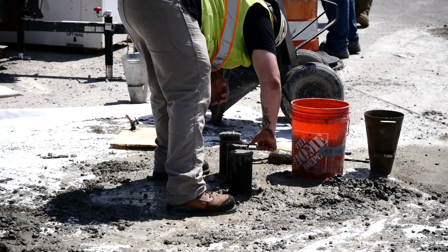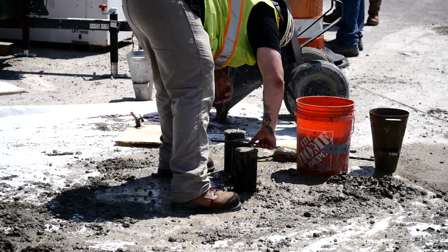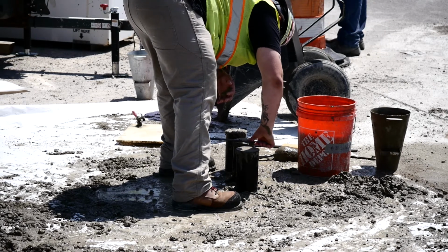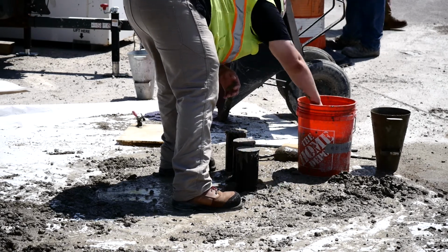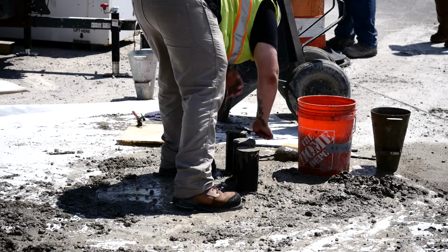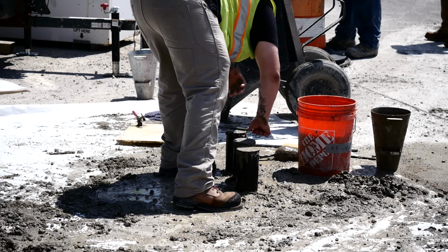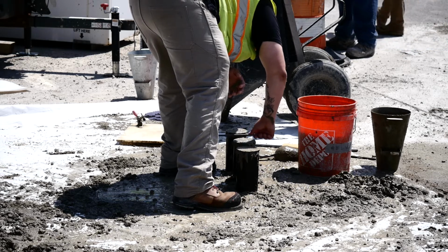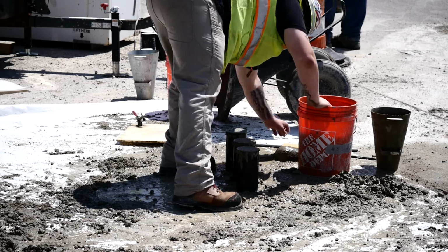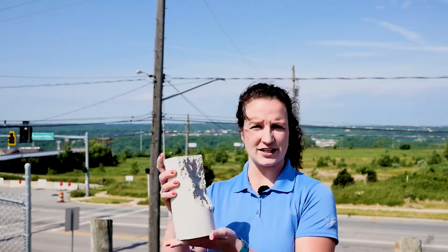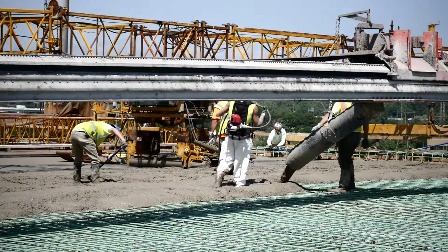The final test that we do is we test for the compression and the strength of concrete itself. So we make cylinders, and once those cylinders are made, we let them cure and we break them after 28 days. And once we do the compression in our test lab, we're able to determine the final strength of the concrete. Here's an example of one of our cylinders that we did break. And this actually broke at a strength of 4,200 psi. So that's pounds per square inch.